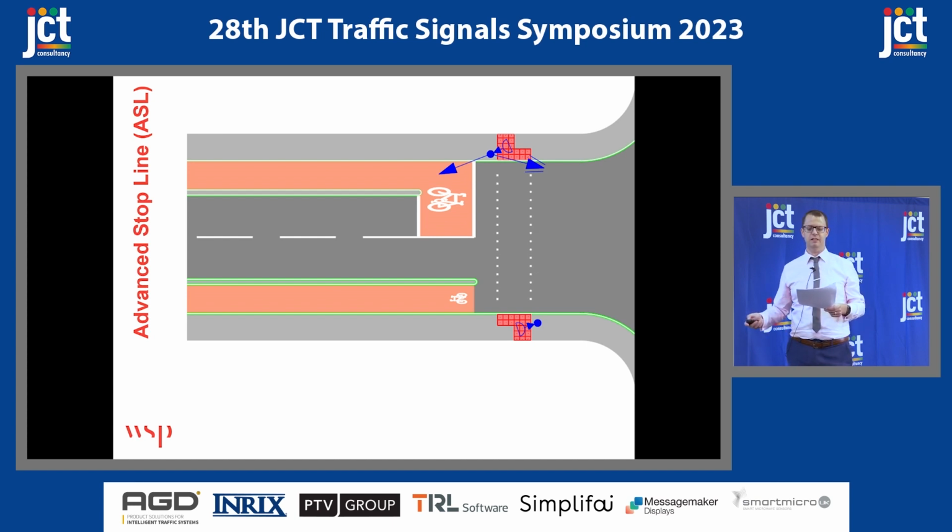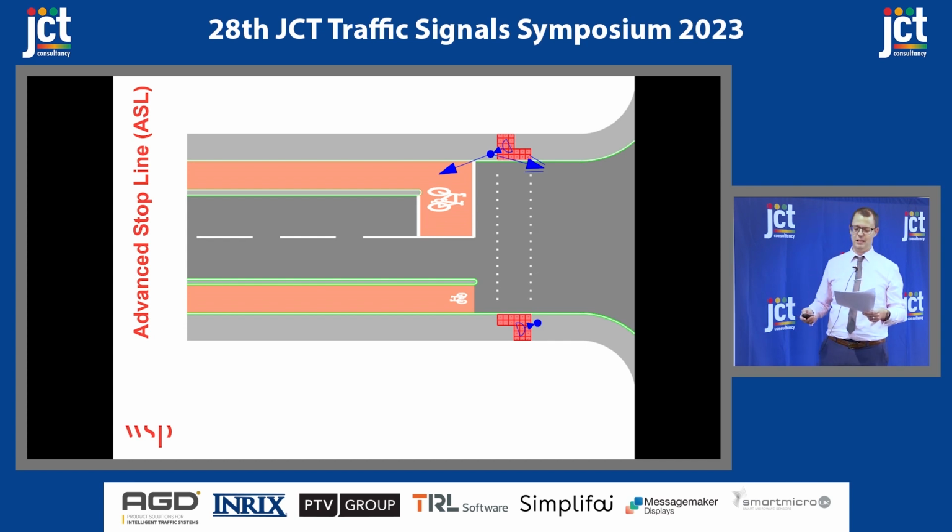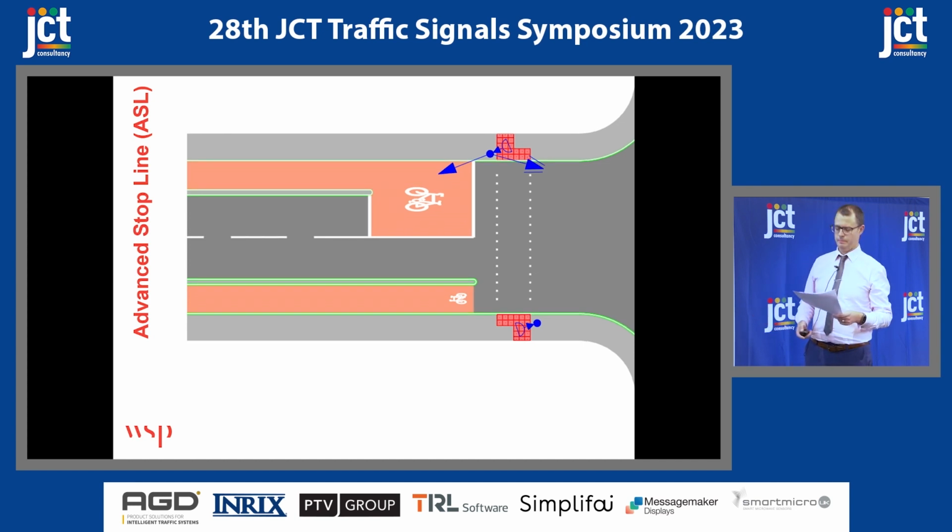I don't think I've ever seen an advanced cycle stop line area that isn't 4 metres long. Maybe I've led a sheltered life. But TSRGD allows it to be increased to 7.5 metres. That allows more space for cyclists to move over to the right if they need to, especially with the segregation, meaning they can't cut the corner anymore, so let's do that. Right, so all this helps cyclists that arrive at a red signal get ahead of the stopped motorised traffic. But they all get released at the same time, so are immediately in conflict again by the time they get into the junction.